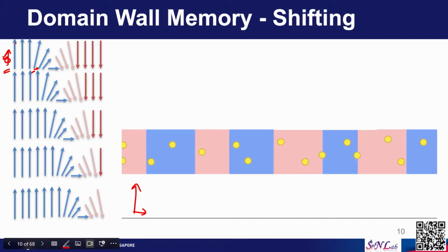Okay. So, there will be a spin torque transfer between this spin and this particular spin. Because of that, the angular momentum transfer will happen. So, this spin becomes up. You can notice that instead of being at this angle, this spin has now received some angular momentum from this electron and it has gone up.